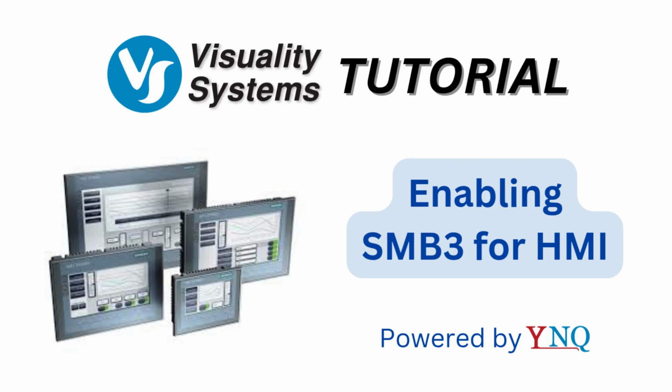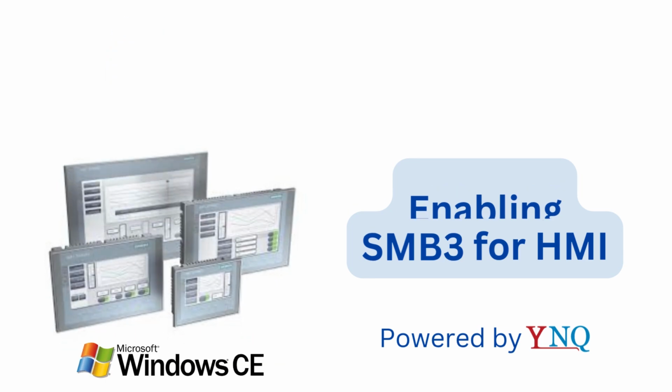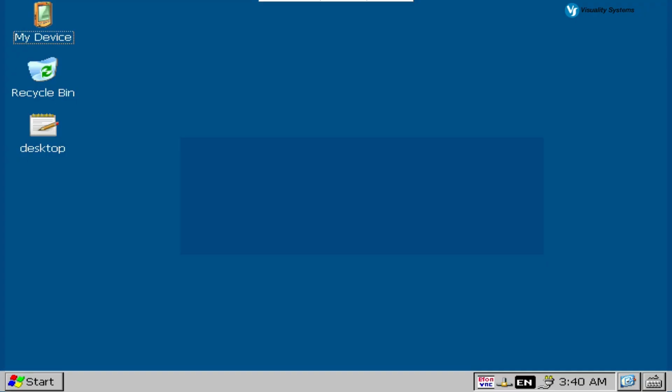In this tutorial, we'll walk you through how to install, activate, and configure our SMB3 for HMI solution, enabling legacy SMB1-based HMI systems like Siemens SIMATIC WinCC and Windows embedded compact panels to connect to secure SMB3 servers. Let's begin by installing the software on your HMI panel.